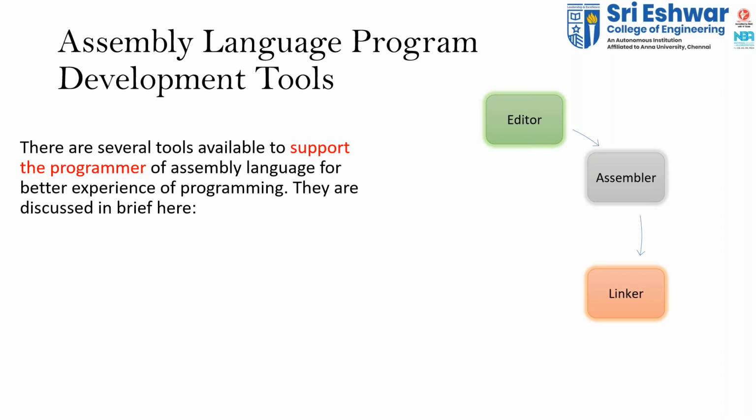I explained the assembler in the first laboratory session. I hope you all remember this. In the assembler phase, we have some list files and some other files at the back end, which are generated while creating my program. I link those list files and library files using the linker. Finally, we have the locator, which is used to locate the memory location for my program.